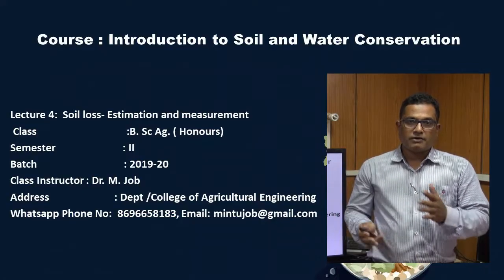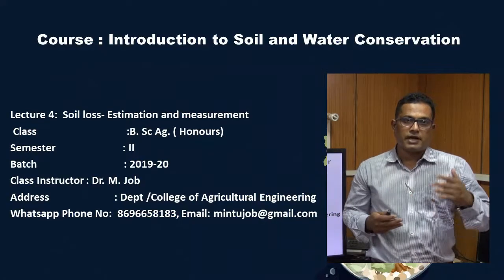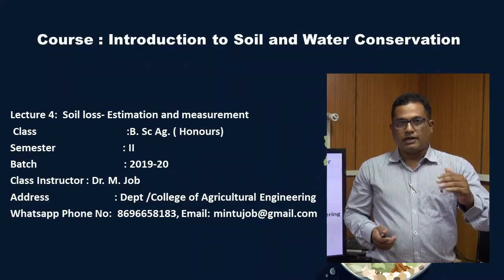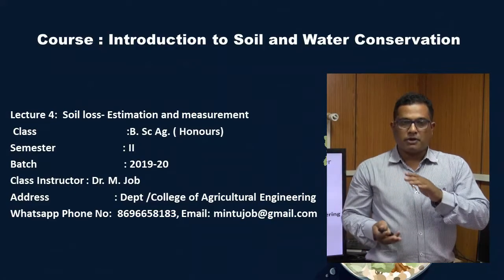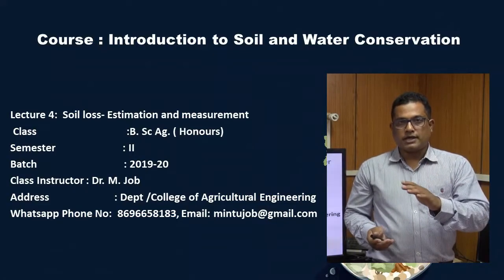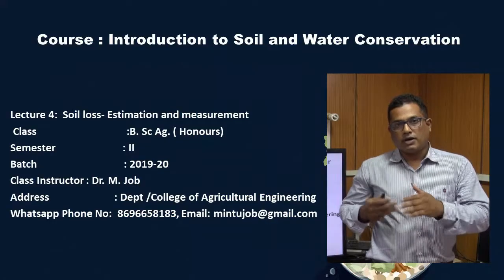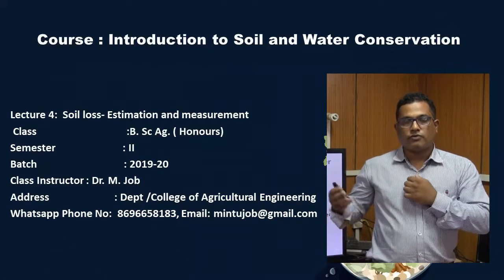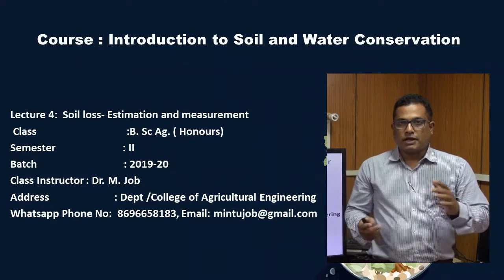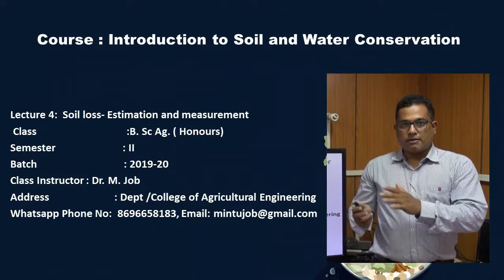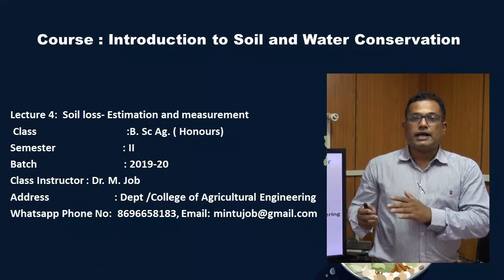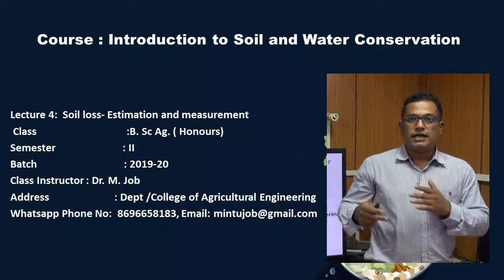The turbulent water coming as a result of runoff will first go to the sedimentation tank, which has a certain depth, maybe 1.5 to 2 meters. It will get deposited there, and then it overflows into the tank or dam. Here the turbulent water is allowed to settle down. That's why we call it a desilting basin.